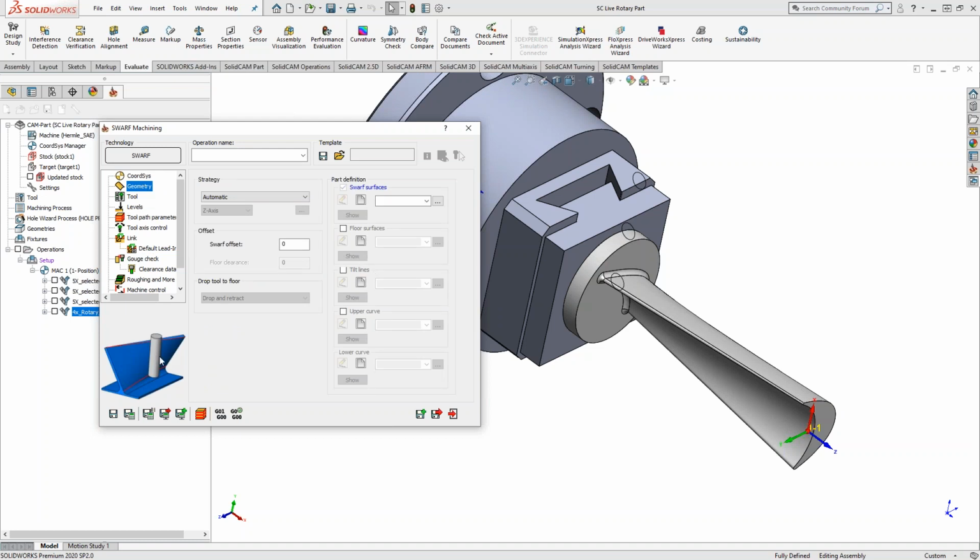This one is purely for this sort of shape here, whereas if I have something that actually changes shape in the profile, I like to use the simultaneous one. But this one actually is pretty useful when you have this exact sort of side of the tool following that exact curvature there. You define it using the same thing. You just choose your surface, and then you can define it as following the floor. So you can see there, once we choose the floor, it gives it the proper tilt. You can give it tilt lines, very similar to what we were just talking about. So you can generate face curves on the curve, or you draw your own lines in there, or you can do it by the upper curve and lower curve. This right here is very similar to morph between boundary curves, where you choose the upper curve and the lower curve, and then it makes sure that the tool vector passes through both of them.